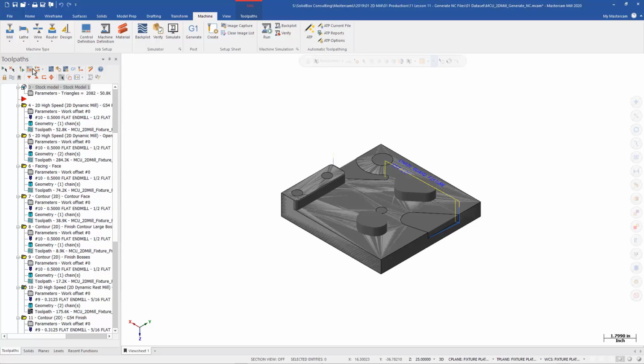So from here, we've covered pretty much everything across the board. Mastercam's interface, from setting up a program, from Mastercam design tools, understanding how we deal with levels, geometry and solids, and then we got into programming the part with some basics and dynamic toolpath motions, and talked about radial chip thinning and all the things.